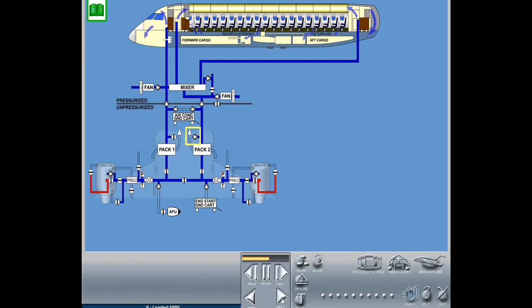The Pac-2 ram air ventilation consists of a check valve installed in the emergency ram air ducting that connects the ram air duct to the Pac-2 outlet ducting. The emergency ram air check valve does not require electronic control. The emergency ram air check valve will be open whenever the pressure in the ram air ducting is greater than cabin pressure.